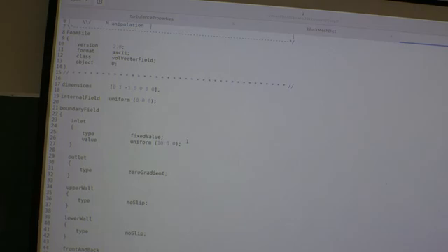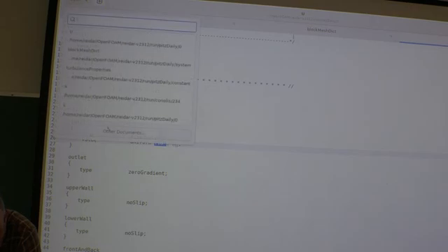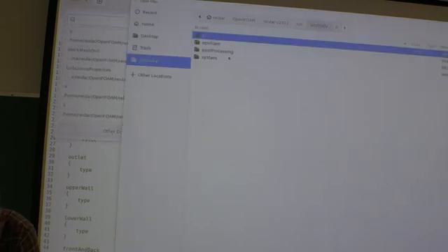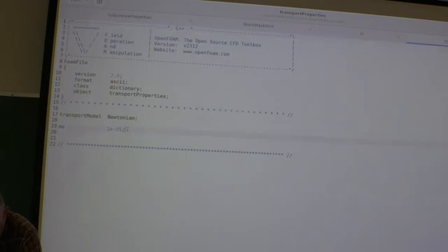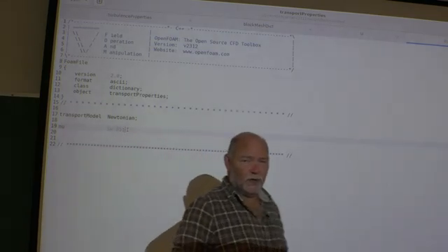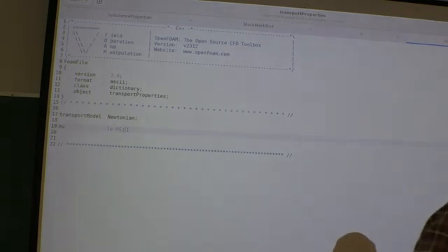Now, while we're here, let's have a look at the Reynolds number. The opening, I think that's roughly 1 inch. And we have now a velocity scale of 10. Okay? Then the only thing we need is the viscosity. Where do we find the viscosity? Constant, and then the transportProperties. Okay, so it's 10 to the power of minus 5. So we have 10 multiplied with 100,000, that's 1 million. And then we multiply with 0.025.